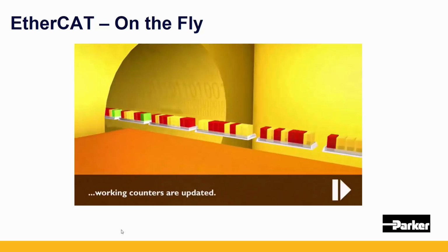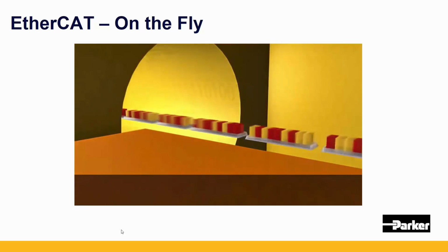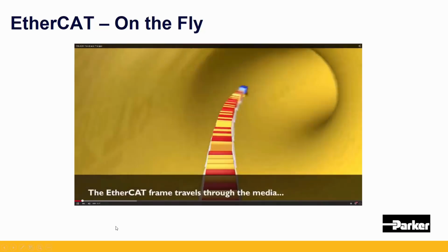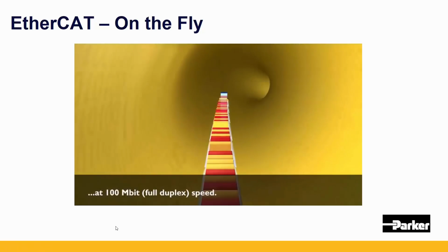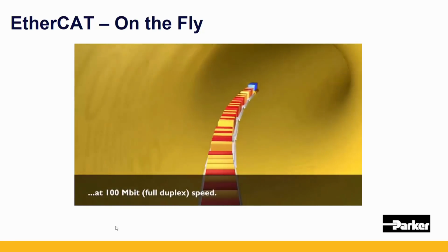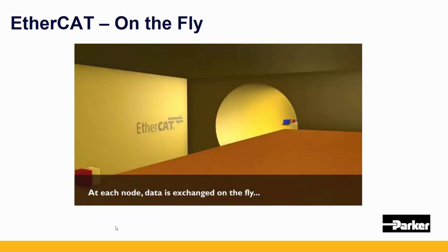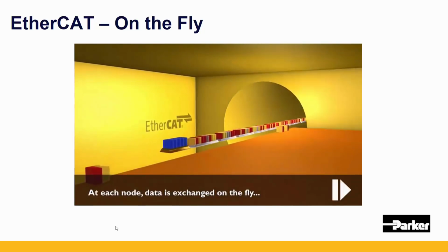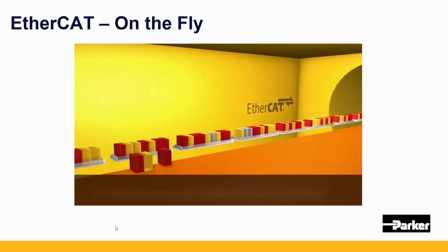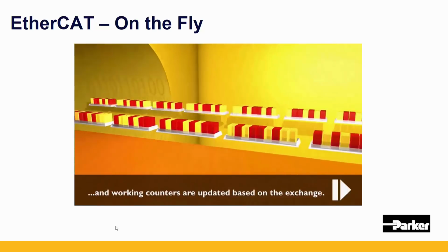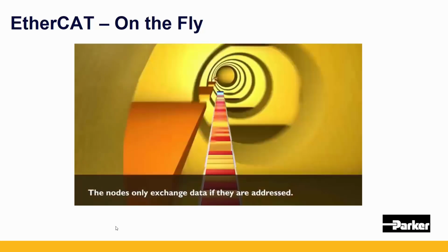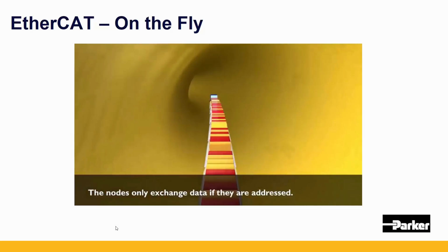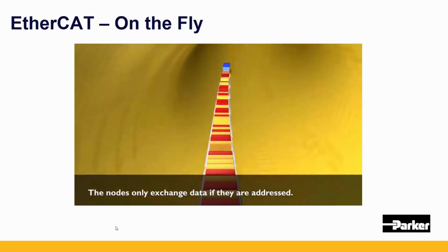The other reason why this is possible is because the data is going to be written at a very, very specific location. Let's say that the data that we're trying to transfer around is people. And so they know what stop to get on and they know what stop to get off. So Ethercat is very much in the same way, where it has designated locations along the packet where your first device would be written to, and it has very specific places in its packet where device 1 knows that it's going to read from. We can just simply pass the data, and I can simply just count the bits by and say, oh, this is where I write to. And likewise, oh, this is where I read from. And the rest of the packet we don't care about.